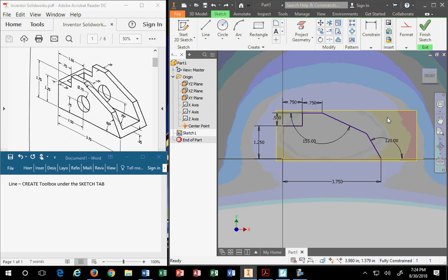I don't want to have to delete the 155-degree angle in my detailed drawing and put in the 25-degree angle that the customer really wants to see. Got it? The customer didn't tell me this is 155 degrees. They said it's 25. Their tolerance is attached to the dimension that they care about, not the dimension that Inventor dropped on your model. Do you hear the way I said that?